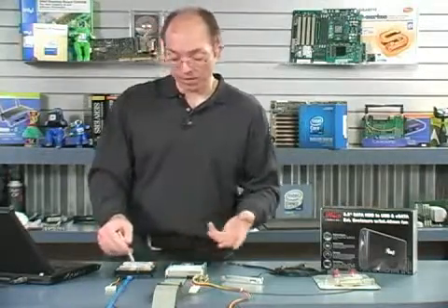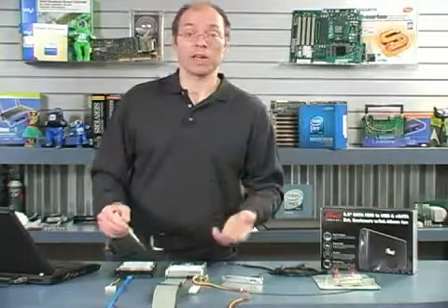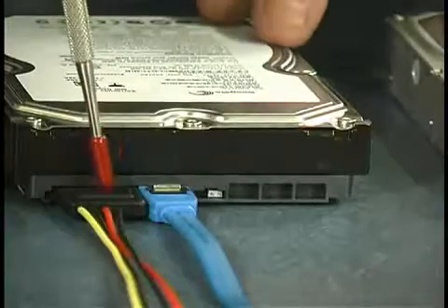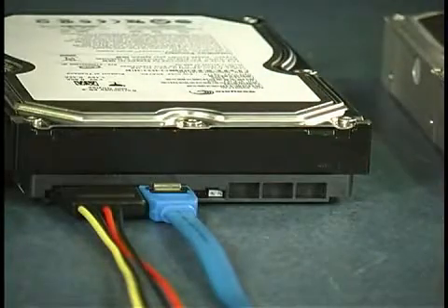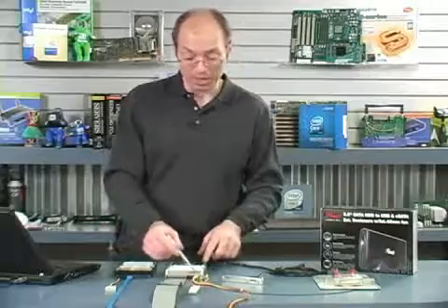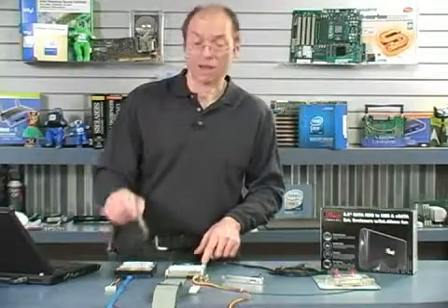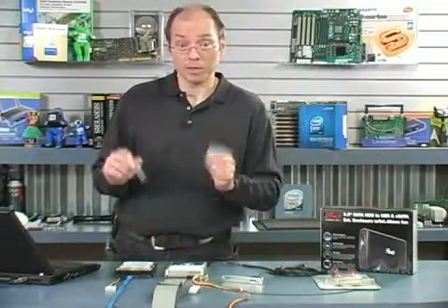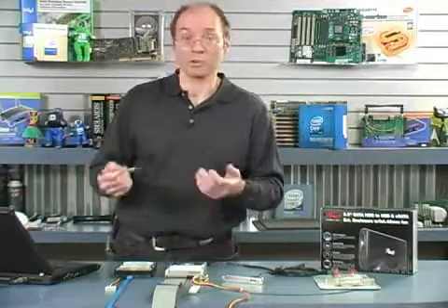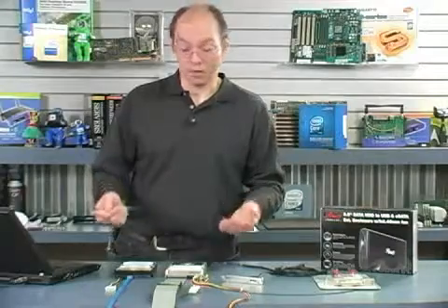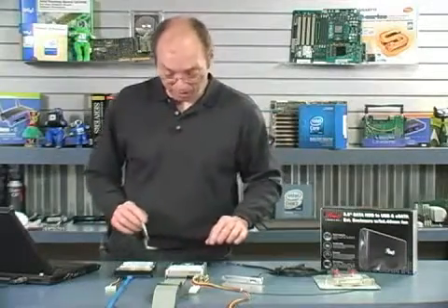I kind of liked it when they did because oftentimes I was running into power supplies that didn't have the sufficient number of serial ATA power connectors to power all the drives I wanted to put in there. And when the drives had both, no problem. I could use the older style power connector to provide power to the drive. The important thing to note was you just can't plug 2 power connectors into one drive. That does not work. In fact, it can cause damage. So that's just a warning there.